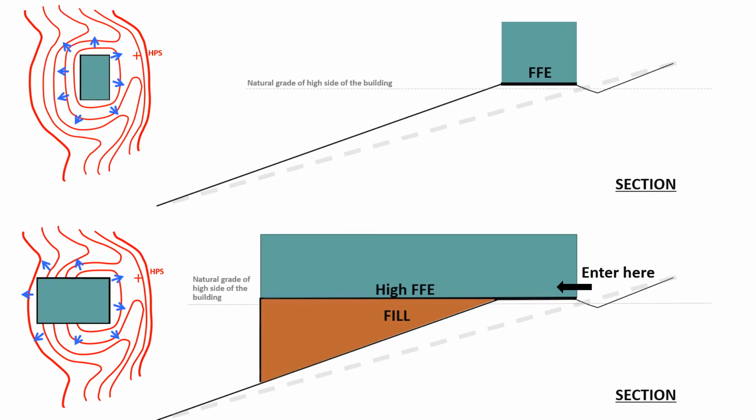What if the building is even longer? Then your pillars need to be higher, or the amount of the fill will increase, right? So this approach could cause a lot of problems. For example, the construction could become too expensive when the pillars get too tall, or the amount of the fill becomes massive. The building will appear overly heavy as well in terms of its aesthetics.